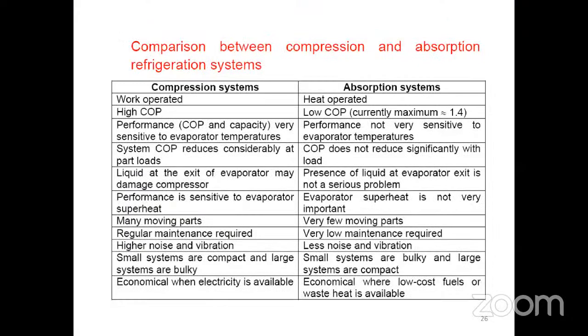What is the comparison between the vapor compression system and the vapor absorption system? Work operated, heat operated. High COP, low COP, currently a maximum of 1.4. Performance very sensitive to evaporator temperature, performance not very sensitive to evaporator temperature.